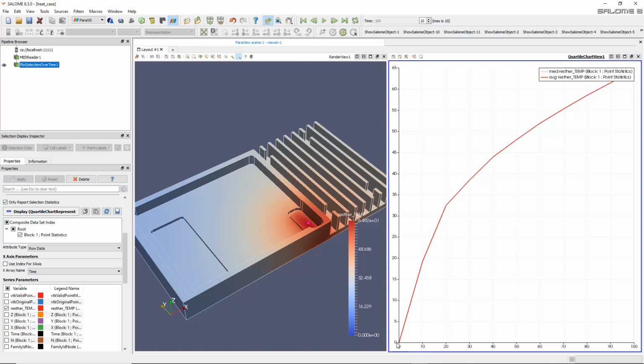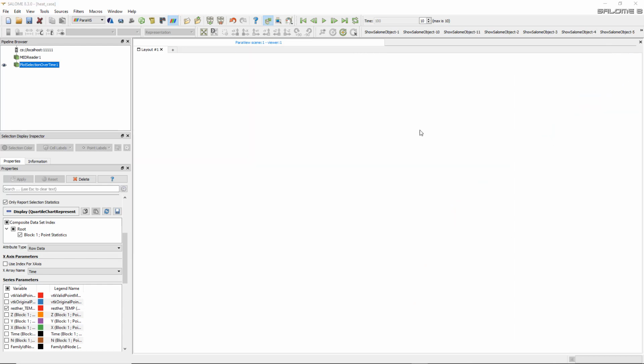But this time distribution is not increasing exponentially anymore. It's basically increasing, and we see that it starts to kind of converge towards a certain value. And we know, because we did the static stationary analysis, that the final value should be 140 degrees. So we start pretty far here. We are at 64. And this basically means one thing. It means that the time 100 seconds is too short to actually get the final stationary result of this analysis. So I have again to go back and recalculate.